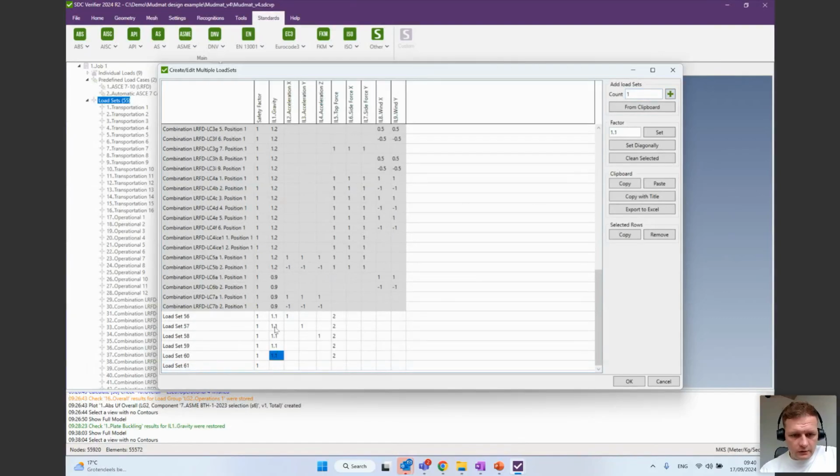Did I do that? Yeah, 61, and copy these values from here, paste it here, and I don't know my exact value of top force. So maybe the factor has to be not 2, but 64. It is possible to save time on analysis because it's done after the solver. It's just multiplying the outputs with the coefficient and the partial load factors. So yes, it is possible, and this is one of the very strong features.